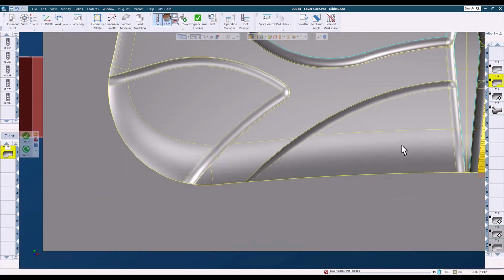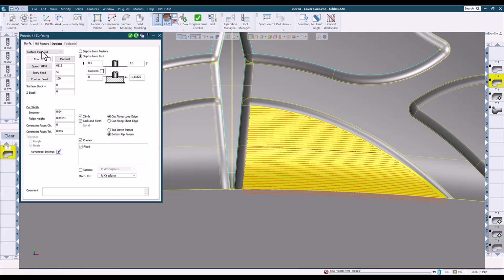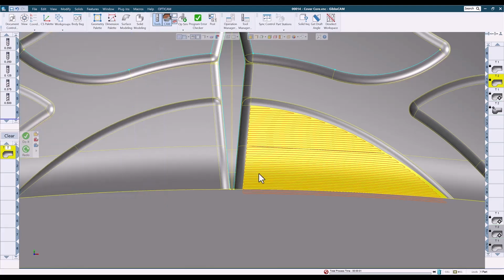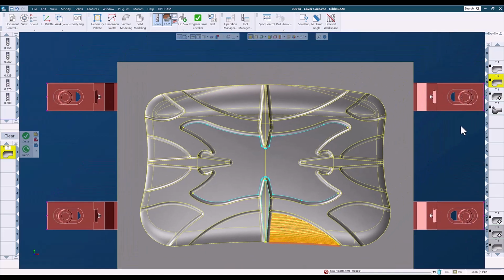This toolpath is also from the surface process, and it's a surface flow cut, which is a single surface toolpath that's controlled by the ISO curves of the surface. This toolpath will automatically run parallel to either the U curve, which would be considered the short side, or parallel to the V curve, which would be considered the long side. With a couple of exceptions, it's not ideal for multiple faces since it will machine each face separately, but it's often hard to beat when you need just a quick toolpath to finish a single surface quickly and easily.